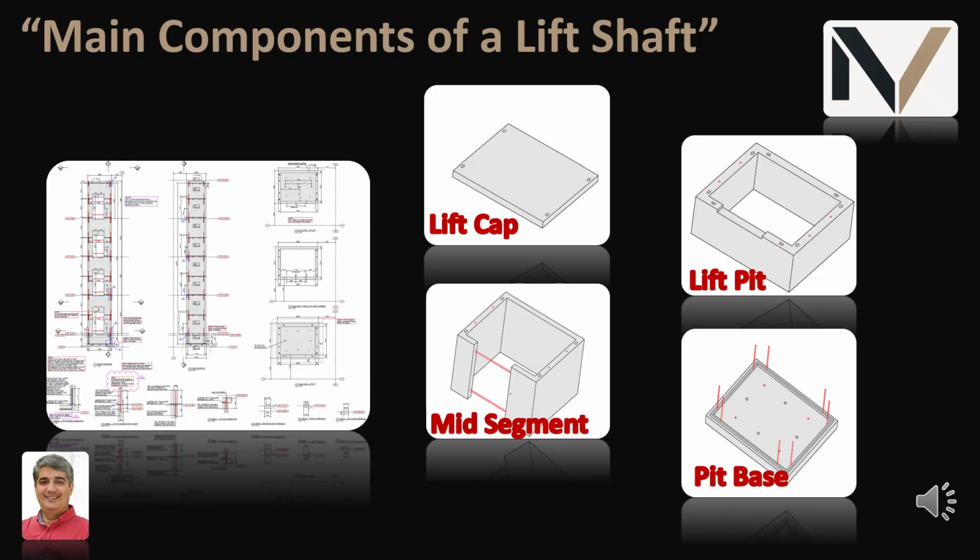On this slide, I have tried to show a general arrangement of the lift shaft on different levels and also a 3D of each of the components. As we discussed earlier: lift cap, lift pit, pit base, and mid segments. It should be noted that the exact design may vary depending on the preferences and requirements of the structural designer.